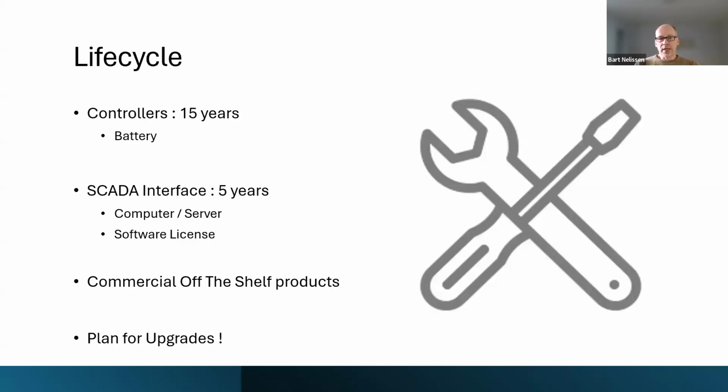And then before we start getting near the end of today's presentation, I wanted to talk about the life cycle. And as strange as it may sound, even at the moment when you start designing a control system or a SCADA system, you really have to plan for the life cycle and the fact that a SCADA system needs maintenance and it needs upgrades and replacements. For example, the PLCs, the controllers, they typically have a lifespan where they will be supported and operational for 15 years. And that sounds like a long time, which it is.